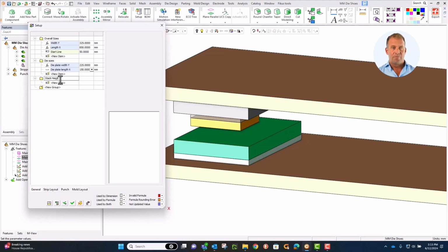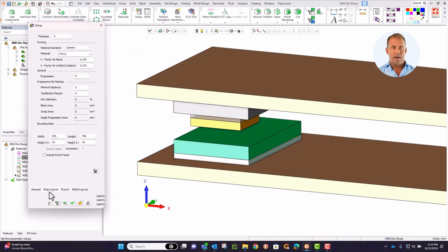When we were working in forming, we used a function called die skin that measured the thickness of the coil. That value is visible in Setup on the Strip Layout tab. To link it, add a nominal value. Now we can link the height of the plane that we made for the stripper assembly in the first video to this thickness value in Setup.